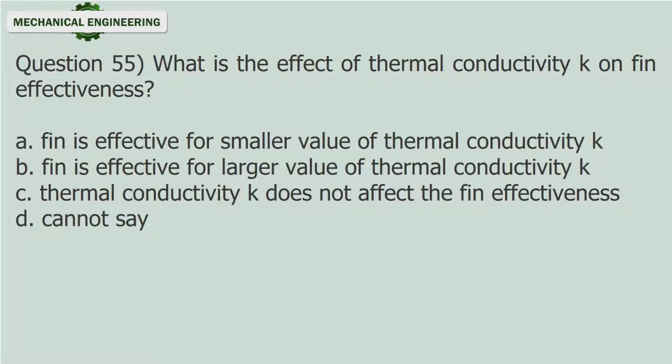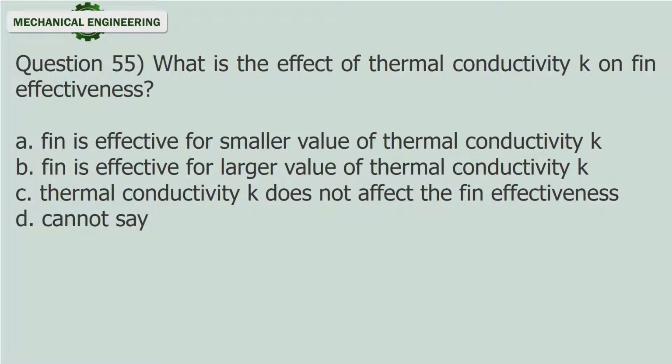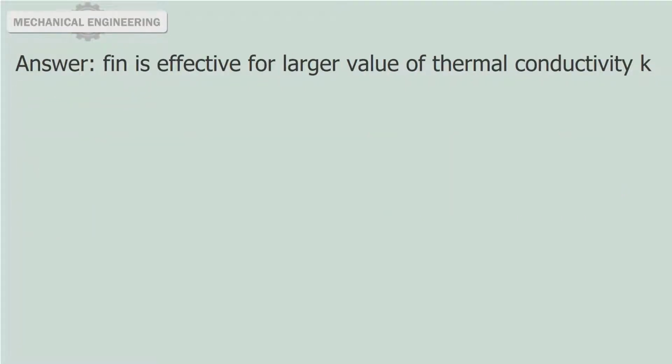Question 55. What is the effect of thermal conductivity K on fin effectiveness? A. Fin is effective for smaller value of thermal conductivity K. B. Fin is effective for larger value of thermal conductivity K. C. Thermal conductivity K does not affect the fin effectiveness. D. Cannot say. Answer: fin is effective for larger value of thermal conductivity K.